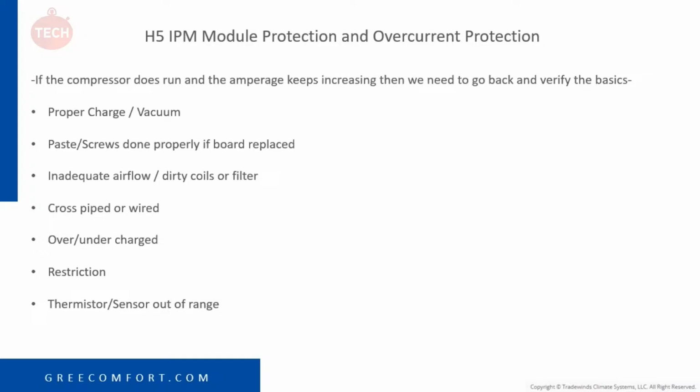Is the unit cross-piped or wired? Is the unit over or undercharged? Do we have a restriction? Or is one of the thermistors or sensors out of range? If the basics all check out and we have a loud compressor, then it may be internally damaged.